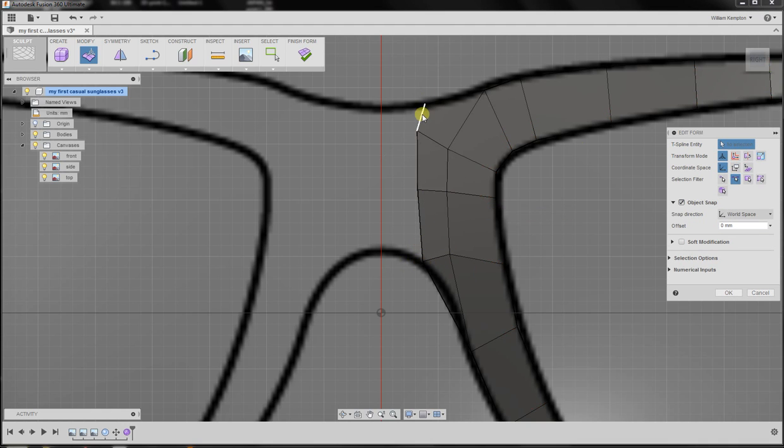And I'll select 3 edges, and I'll hold down the Alt button again, and I'll drag out the remaining 3 faces, and I'll just scale them down in the Y direction, and I'll write 0 in the dialog box that appears, and it should be perfectly straight. And just to make sure that when I make my duplicate group, I'll just place it slightly outside the line, so later on I'll merge the edges.